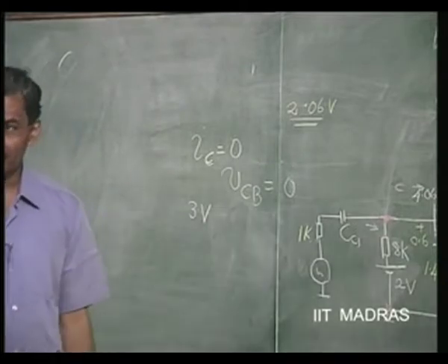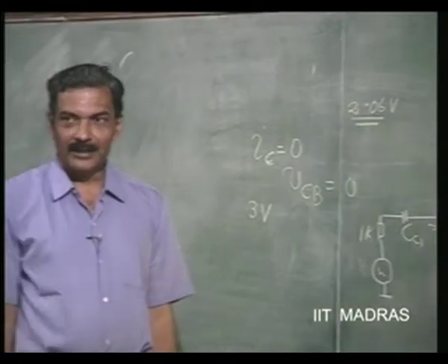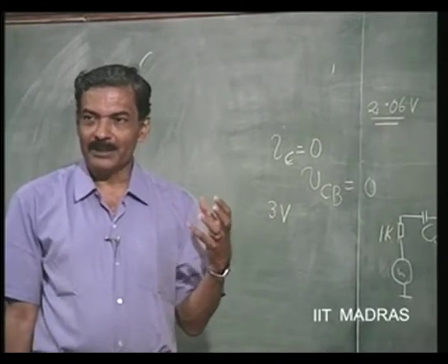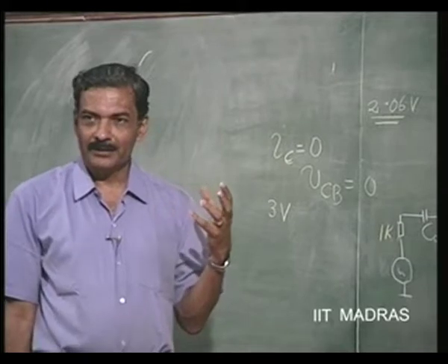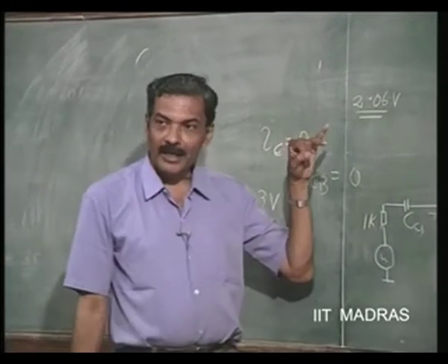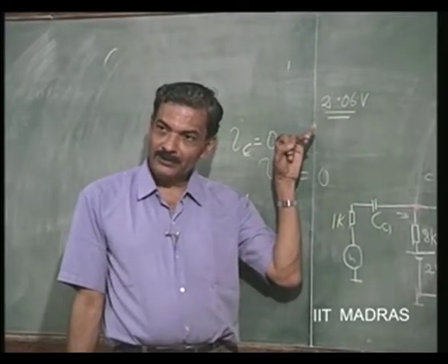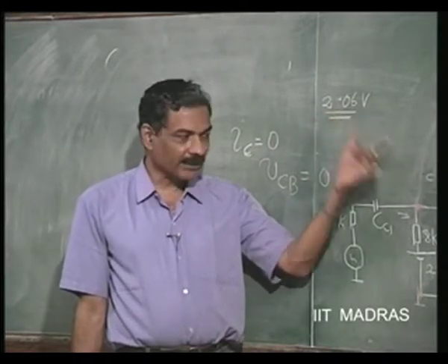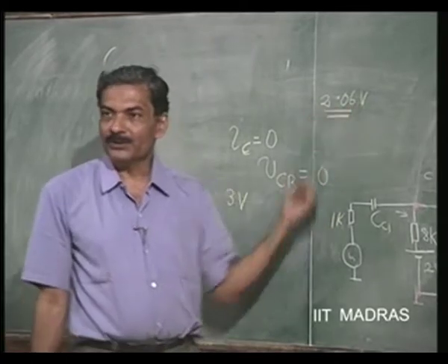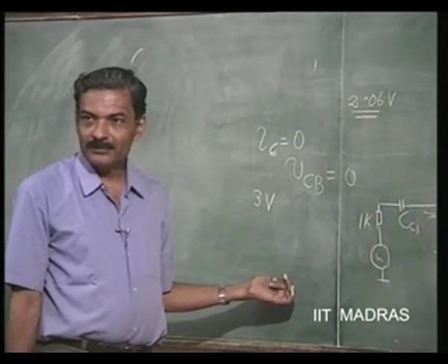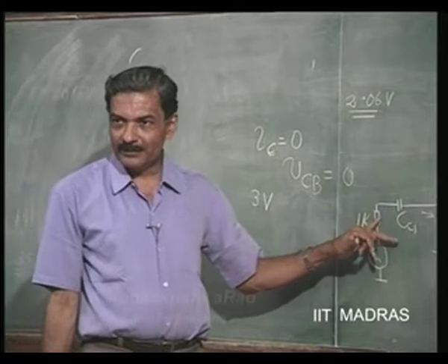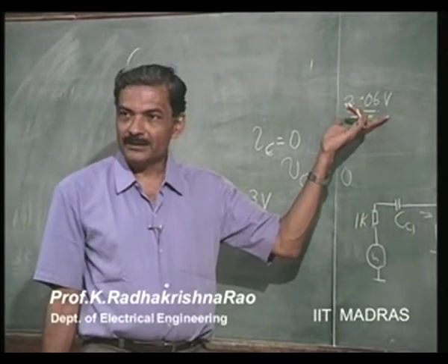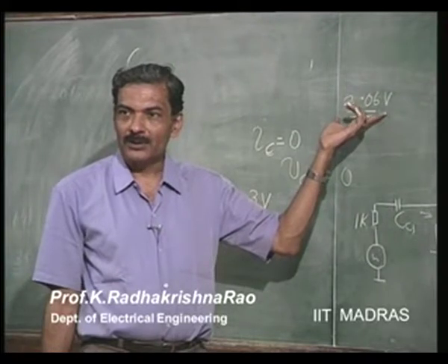It is asymmetric. This is not a design problem where you have been asked to design the operating point such that it is symmetric swing. What it means is the amplifier goes to what? Saturation region. The transistor goes to saturation before it goes to cutoff. If you apply a sine wave, the first distortion that will appear in this case is due to what?